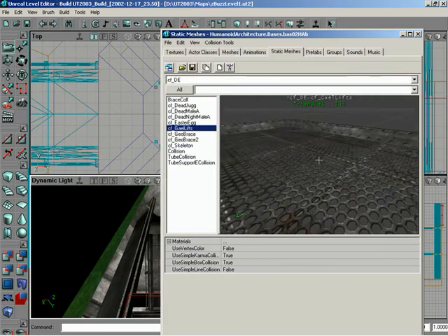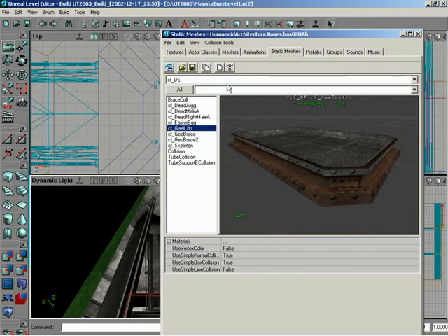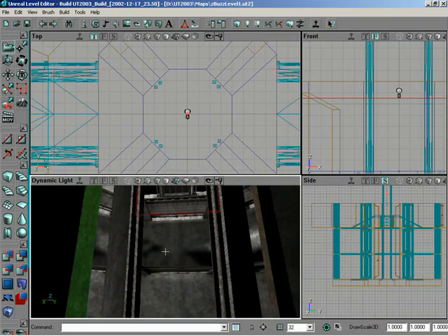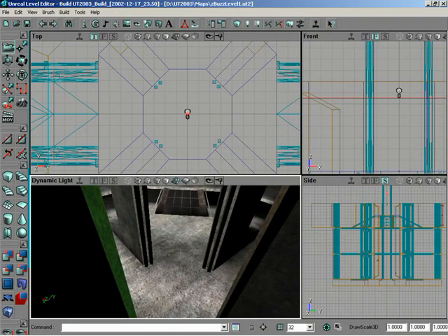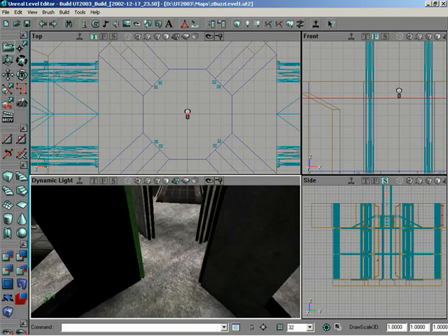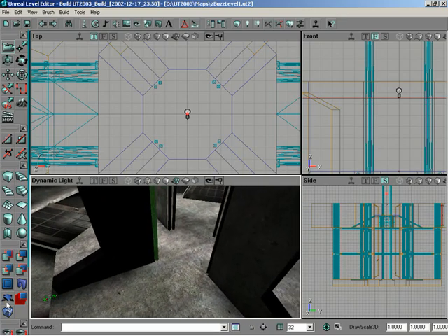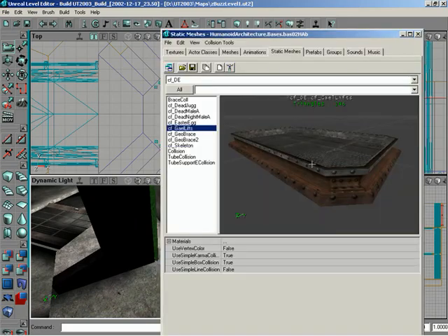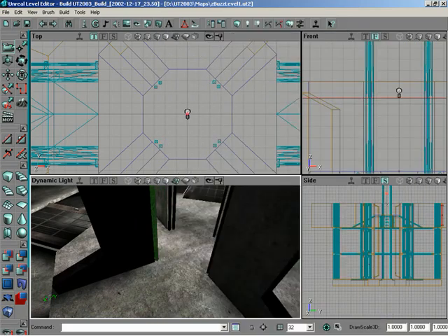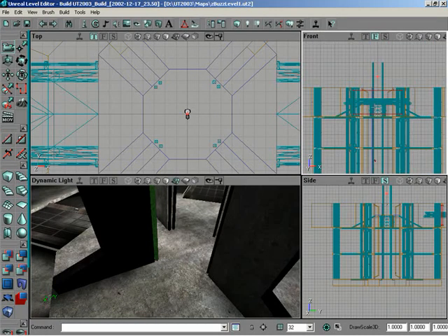And it's going to be the CF_ that one. Gale lifts. Okay. So instead of right-clicking and adding, this is actually going to be an elevator, which is going to move. And in that case, it's a mover. Right, it's going to need to be a mover. This brush here is Add Mover. The way movers work in UT 2003 is they actually take a static mesh and make that mesh into a mover. So with this static mesh selected in the mesh browser, I can then click Add Mover, and if I zoom out a little, it actually added, so it is a mover.